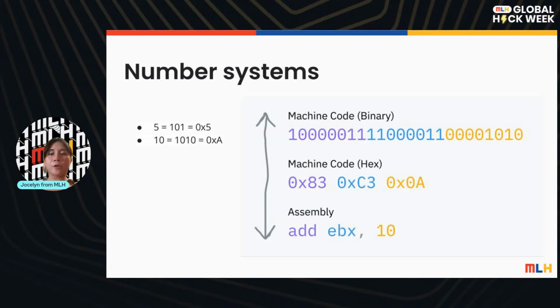So how it works is that you will have your instruction, right? If your instruction is addition, subtraction, loading, or storing into memory, you're going to have a representation of that instruction. The way of representing it is a thing called an opcode, which has 6 bits, a combination of zeros and ones. And that combination of zeros and ones is actually the value that you're going to have.